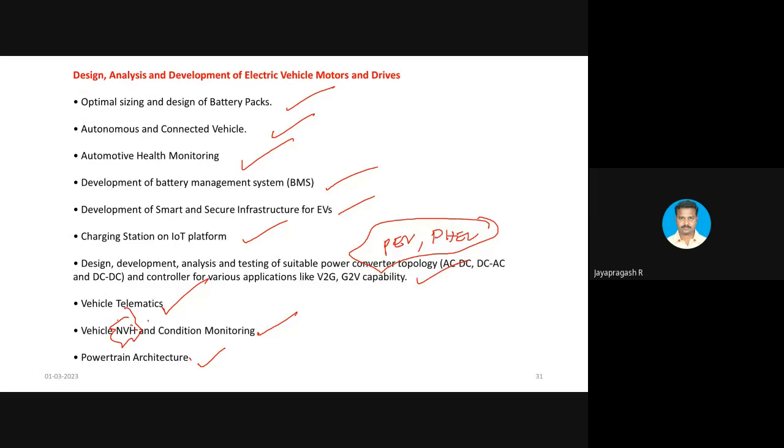How to reduce torque ripple in SRM using rotor and stator parameters? To reduce torque ripple, the first thing is that the pole configuration is most important. Consider the different phases of the machine: three-phase machine, four-phase machine. We don't prefer the three-phase machine, actually, though a few applications use it. Technically, the four-phase machine has more overlap, so the torque ripple of the four-phase machine is lesser than the three-phase machine. If we increase the number of rotor poles, the torque ripple can be reduced.